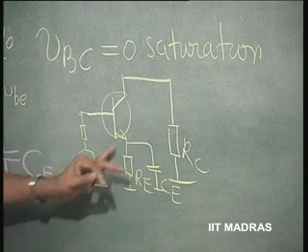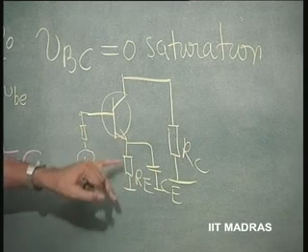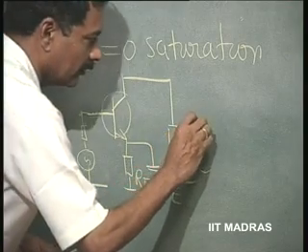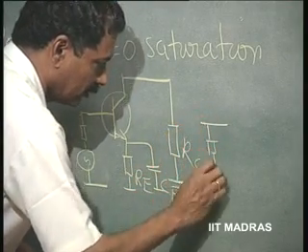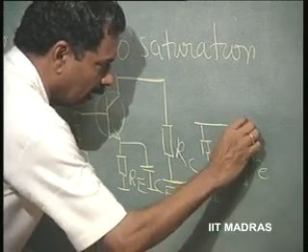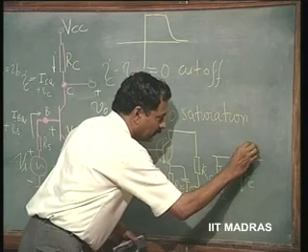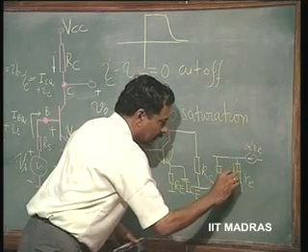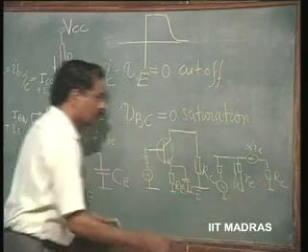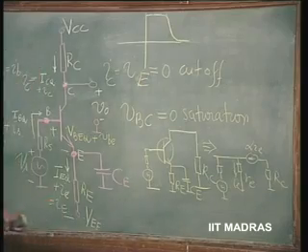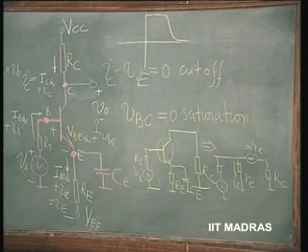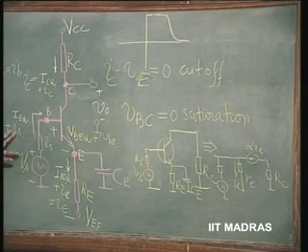Now, the transistor can be replaced by its linear equivalent circuit, where you are going to replace this by small Re, and this by alpha times IE when this current is IE. All these directions you must definitely put. So, this is valid only for these signals Is.